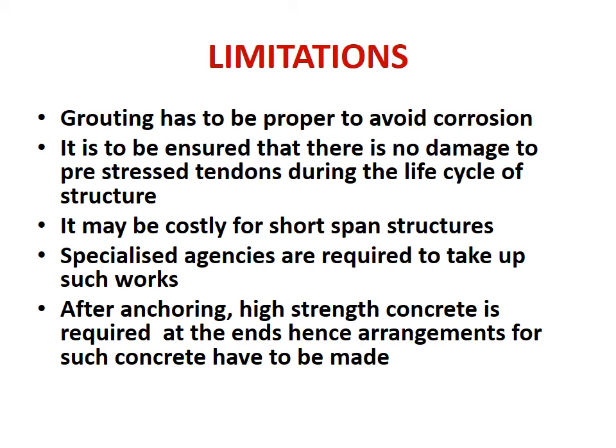For that, you may have notice boards, even signages in such buildings where PT slab has been cast, so that anybody who is coming and damaging or making holes in the slab will be required to consult the engineer in charge. Then only he will do it.